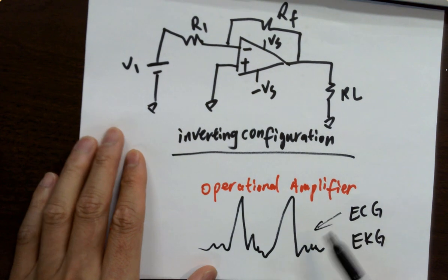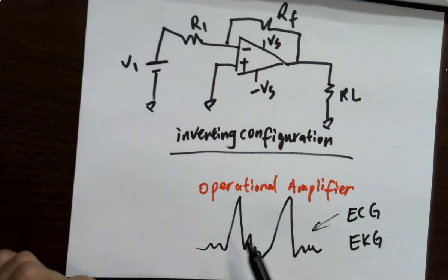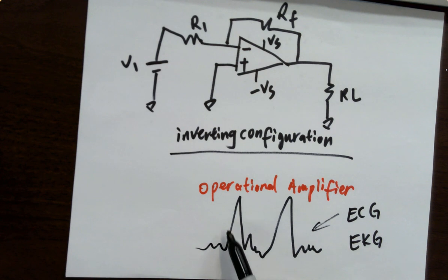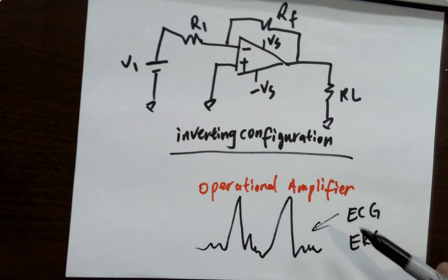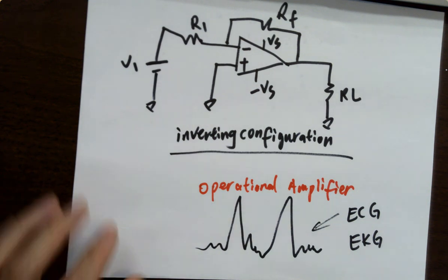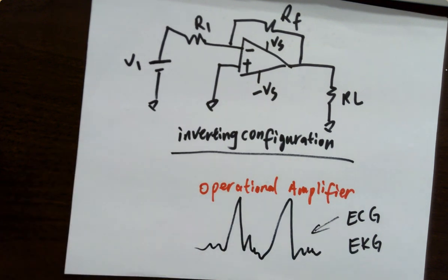It's giving you this heartbeat over here, and the signal, it's a surface electrode, and eventually will be digitized and acquired by the machine, and displayed in the monitor, and this is the voltage signal. It's a voltage signal. And it's not even being converted because your skin is directly giving that charge, and that charge is the voltage signal already. It's a differential voltage. From here, they're doing a subtraction, and the subtraction is this waveform. And it's being amplified and eventually digitized by the machine and displayed.